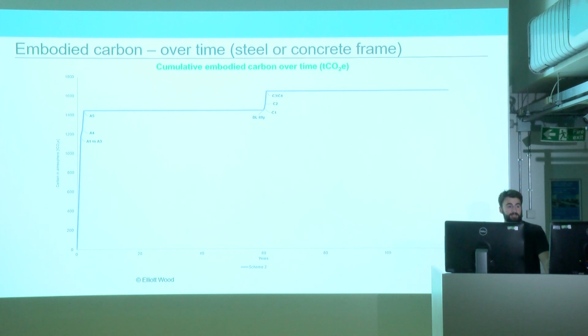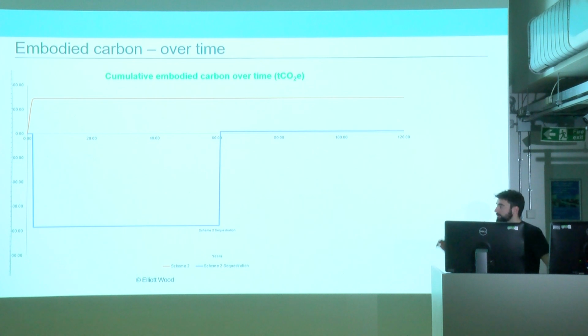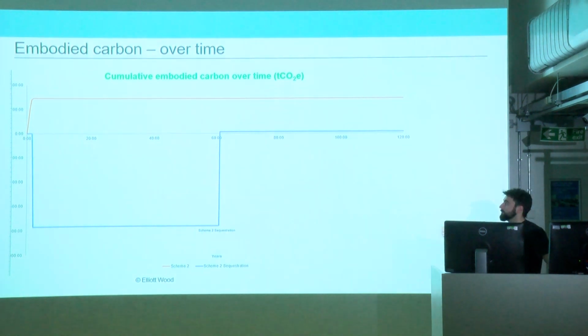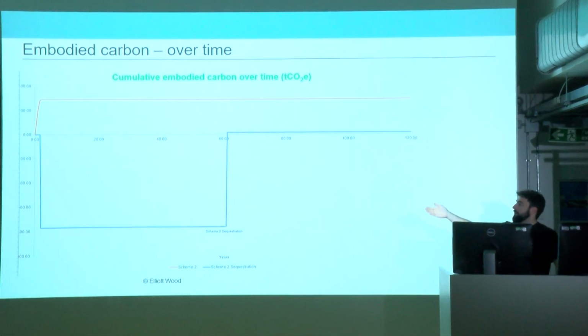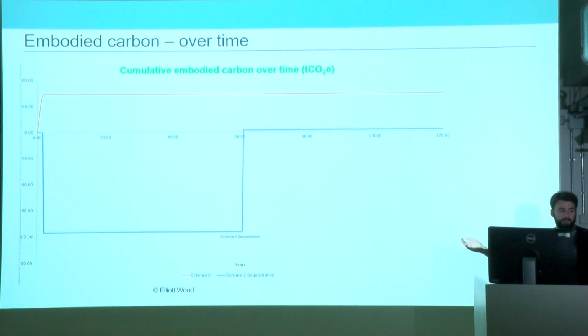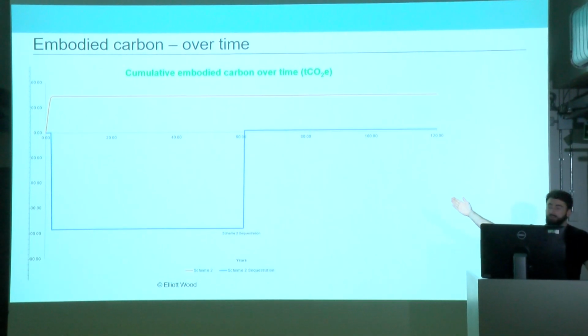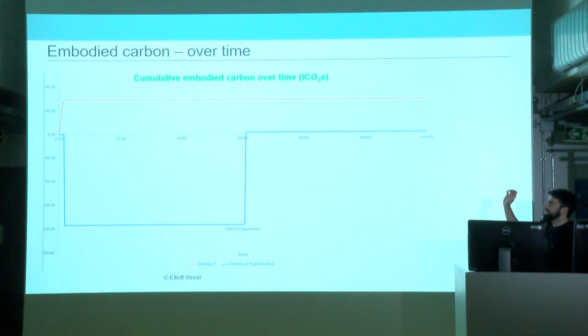How carbon is considered, I'll jump over this slide a little bit and go to this one, which shows that at the beginning of its life, all that carbon is saved already. And as I said, at the end of its life, after 60 years, which is a typical building life cycle, it's released back up into the atmosphere. But comparing that to another project that is not CLT driven, you can see that it's just above the line, using carbon emissions the whole length. And you can see there's obvious benefit savings by going towards the use of timber.